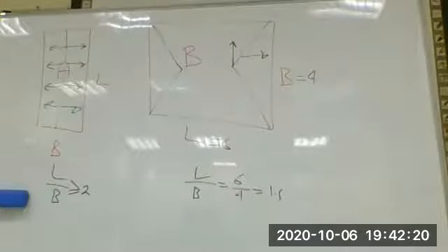If you take the moment at any point and it's not equal to 0, that means this point can be uplifted or overturning or slide. If the moment is not equal to 0, you believe something is wrong. You have to design the system which stands the forces. By question number 2 now, we understand what it means, why we start structure analysis. Why? Now we understand. Okay.